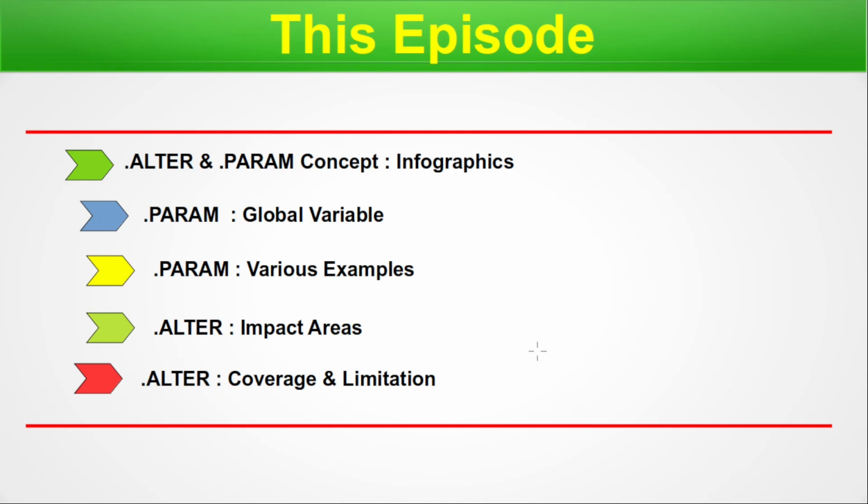Before proceeding any further, I would like to mention one thing. In some of the simulators, it is used as dot alter. In ngSpice, it is used as alter in the control section. You remember we have a control section at the end of the spice deck, which is exclusively for ngSpice. So there we use the alter.